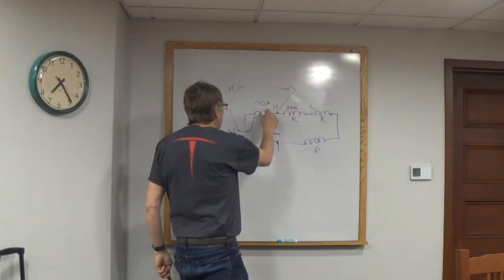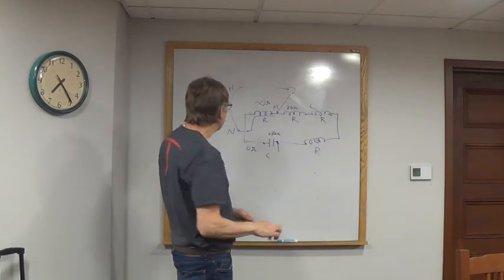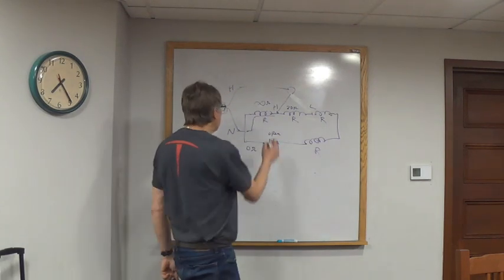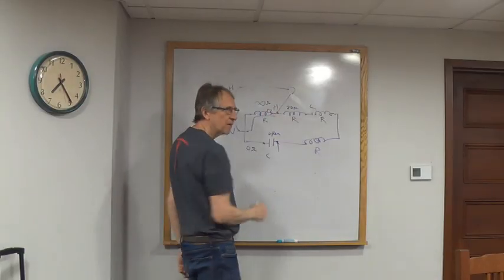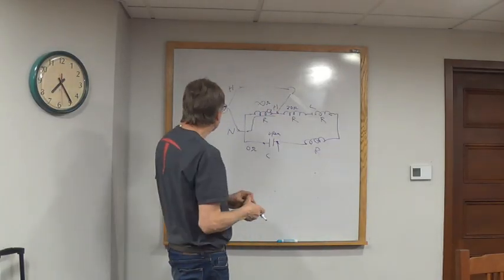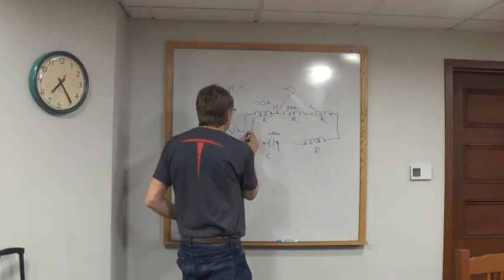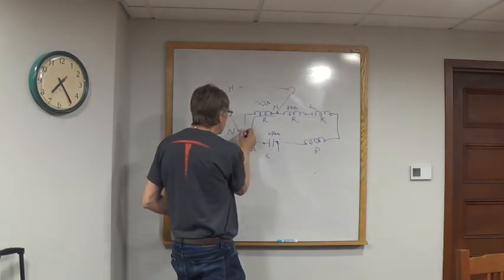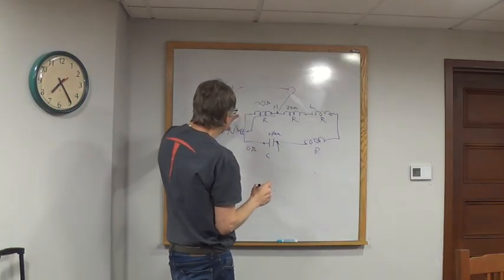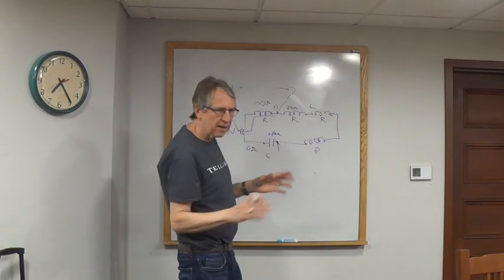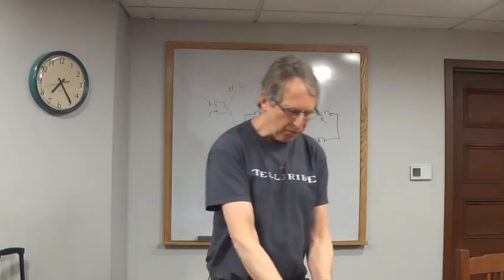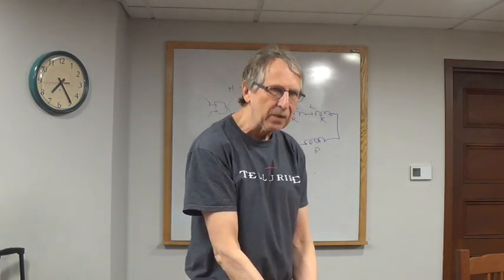There's a break, and that's possibly where the thermal fuse is. The thermal fuse actually typically is not there, but it's all the way here on the way back to neutral. So then you can justify opening the motor and looking for the thermal fuse.